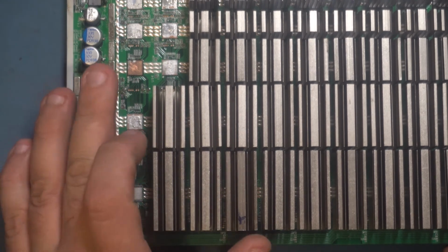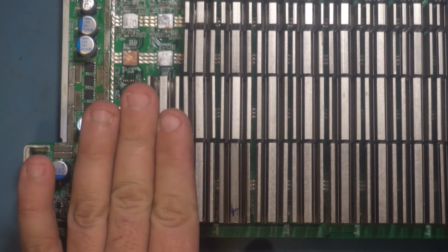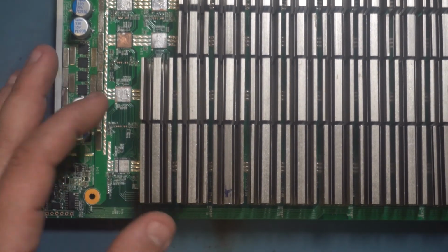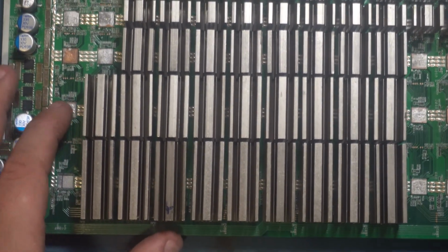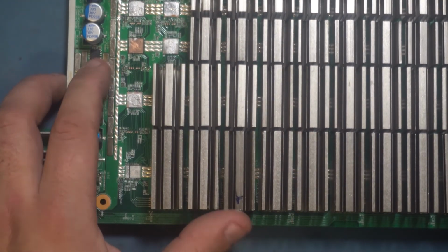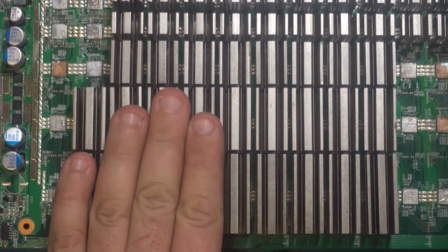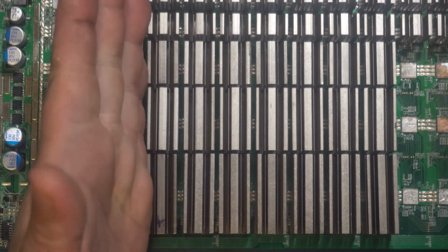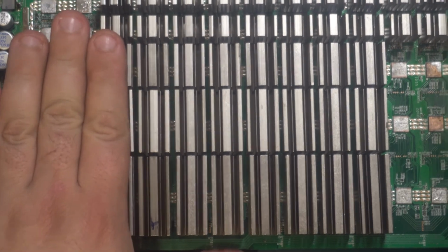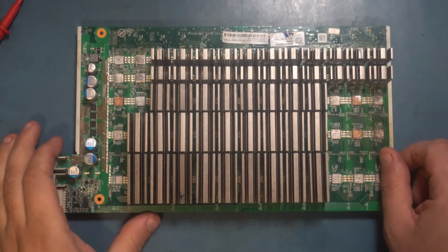So now without the chip on there, the last three domains should not have a 0.8 or a 1.8 volts, I believe. I've never actually done the test, but I believe that's how it should work. But I'm still going to have all my voltage domains because those are generated by the Mosfets. And I'm going to be able to make sure that my chain works all the way up to my third to last domain.